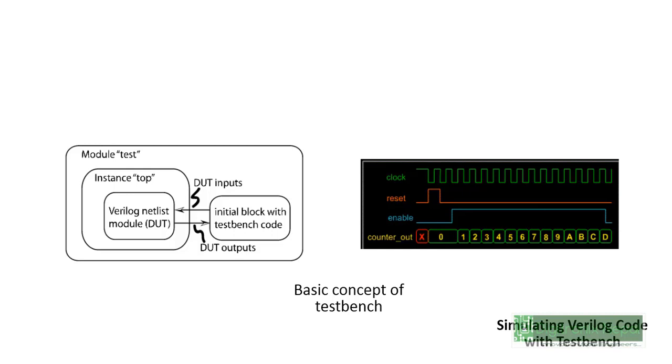So what we can do is simulate that functionality in computer-aided tools or HDL simulators like the Vivado simulator, ISim simulator, Questa simulator, ModelSim simulator, etc. There are lots of third-party and major vendor simulators, and we can test our design on them so we can understand the accuracy of our result. Only in the final scenario can we implement our design on hardware, so we do not need to have hardware every time.